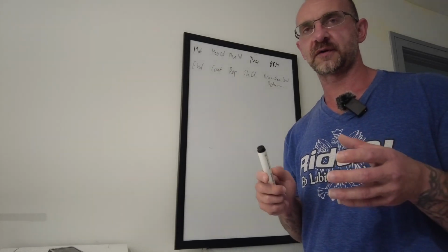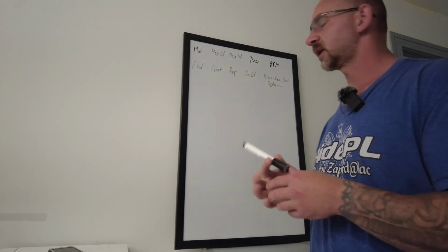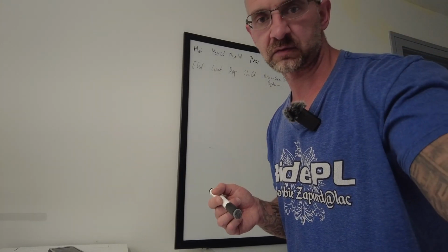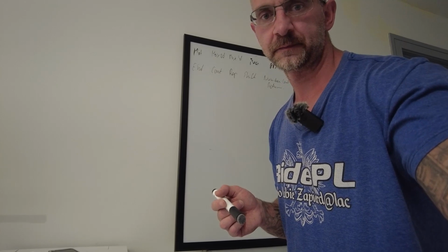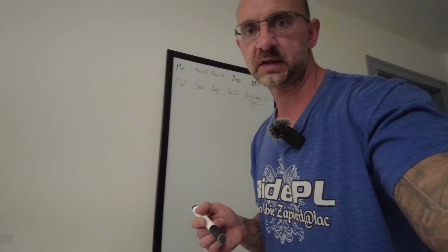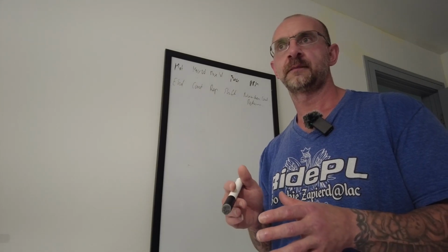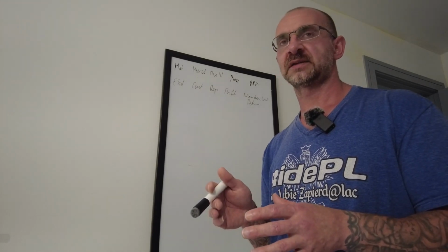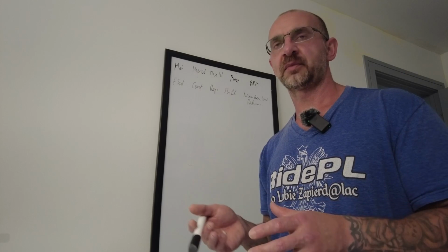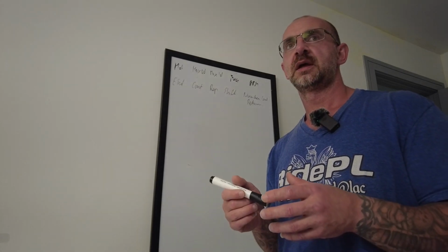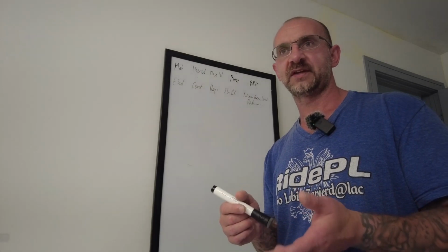So I've recorded a video, because the first thing when you open a Mazatrol, okay, is the material. So I've made a video and I'm going to explain. Technically, the type of material is gonna have an effect on already pre-programmed feeds and speeds.